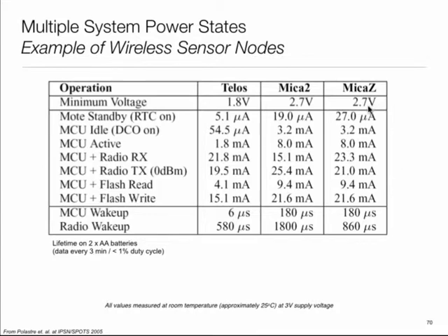What benefits do you think would accrue from a lower voltage? Lower temperature? No. Why do you think? Power saving. Okay, there's power saving, but simply because power is voltage times current. Generally speaking, if I operate something at a lower voltage, then the current will go up. So that power saving tends to be artificial, right? If I have something consuming, whatever, 1 watt, and I lower the voltage, the current will have to go up by that amount.